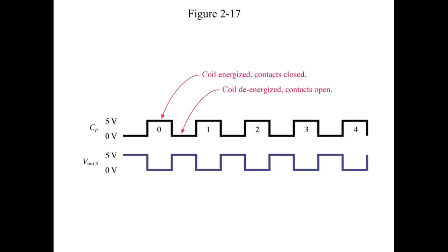If the water company comes out and cuts off the water, or they get a break, all the water could run out of your house, which is not good because it'll go through your meter. Your meter has no idea which way the water's flowing. All it knows is flowing. So what would it do? It would bill you twice, right? Plus suck all the water out of your house. So you should have a check valve on your water system coming into your house.